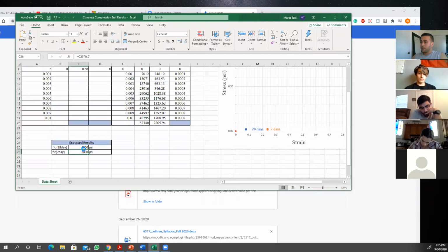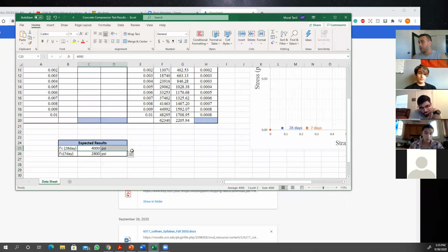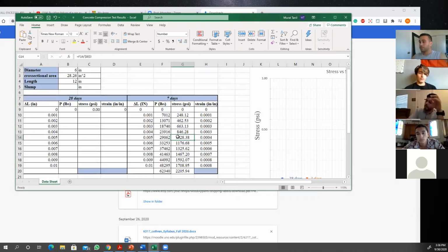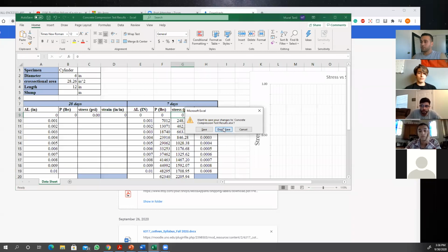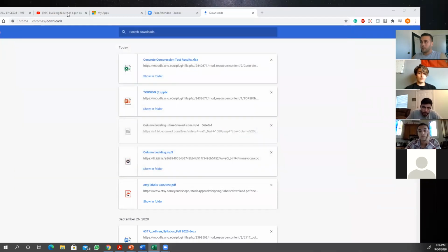And you have your expected results. Like I said, we are expecting to have 4,000 PSI at the end of 28 days, which was advertised on the quick concrete mix. And for 7 days, I was expecting 2,800 PSI, and we got 2,200 PSI. So that's it for the concrete. So once you get these data, load and deformation, you should be able to develop your graph, and you have the sample on the Moodle. But you still have time for this.